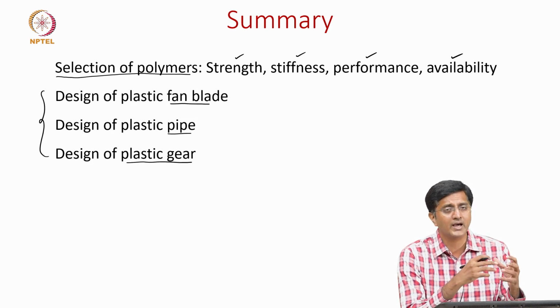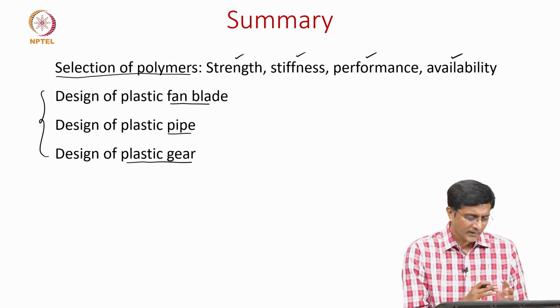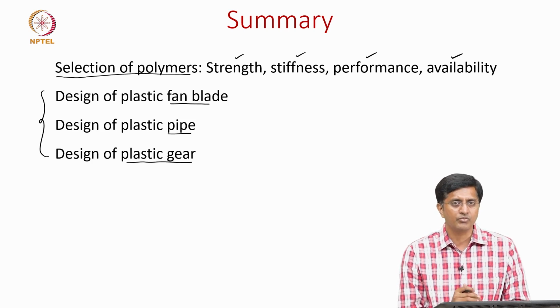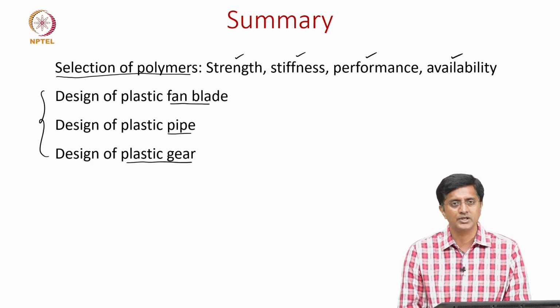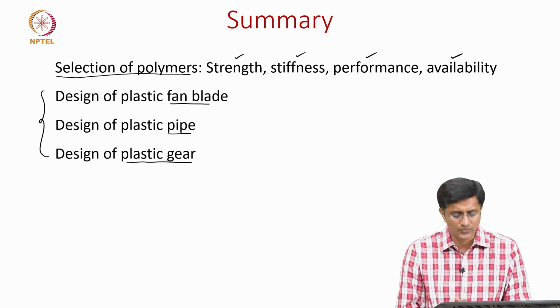But if you are looking at high speed operations, that is when lubrication is a must. But sometimes it is also good to replace one of the gears with a metal because it acts as a heat sink. So, this should summarize what we need to know about a few selection criteria for the gears and a few design principles when we are trying to use polymers in engineering design. With this we conclude this video.